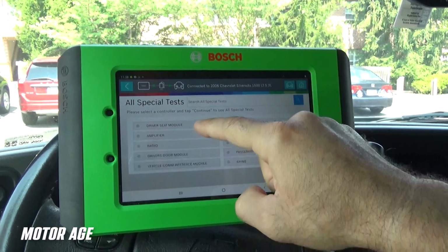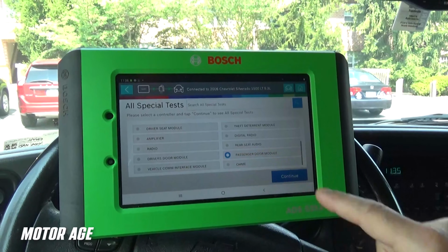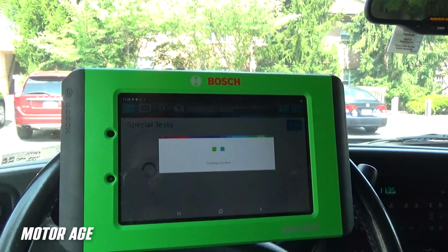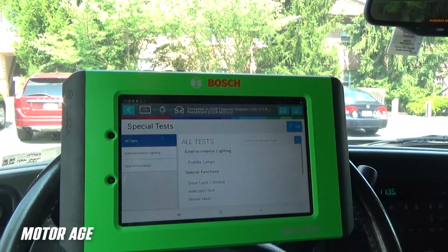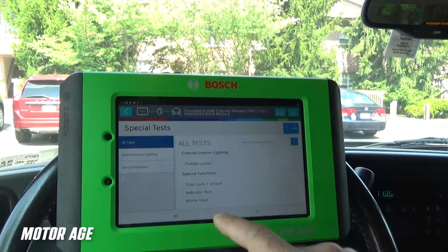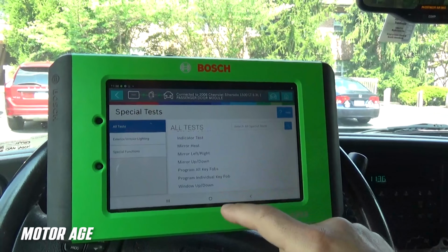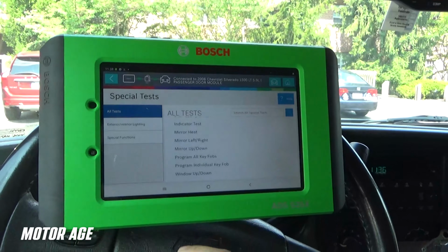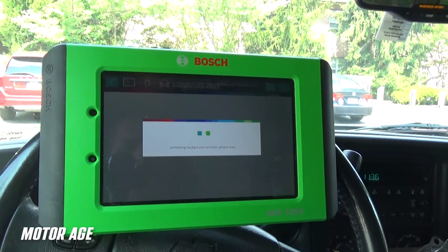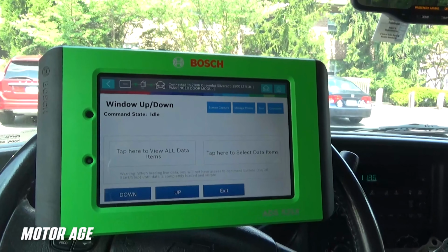We know the driver's side functions. Let's take control of the passenger side and see what we can do. So inside the passenger door control module, we have a couple different functions. We are going to select mirrors, or door locks, or key fobs, or in this case, windows up and down. So I'm going to use the bidirectional control to split the system in half, input versus output.